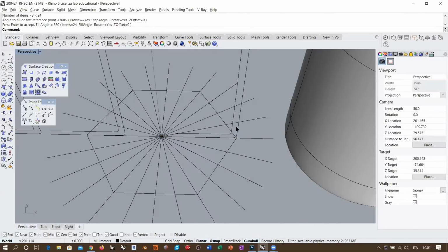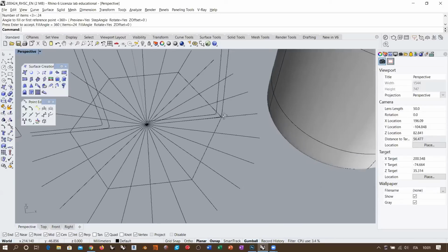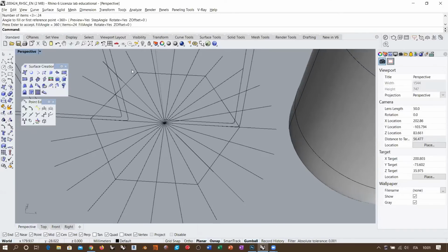Okay, so I need this just as construction reference, so I can create a NURBS curve starting from here, going like to this. Let me turn off the center, having these control points here. I'm using the radial lines only as references to create these control points, to place these control points in a very controlled way. And I'm going to close this line.